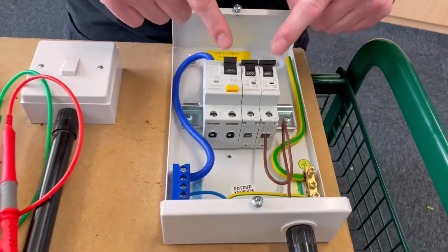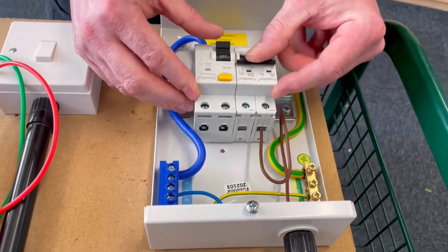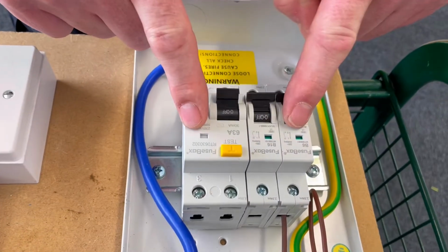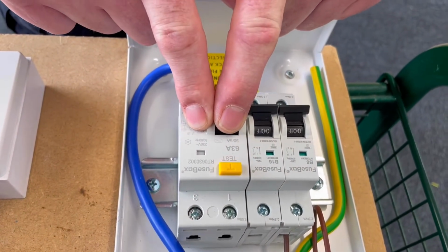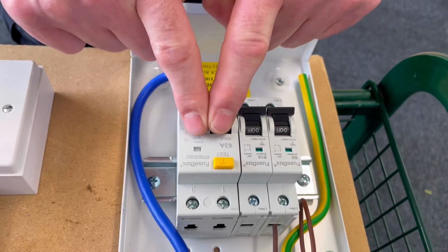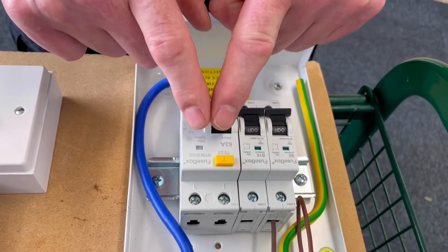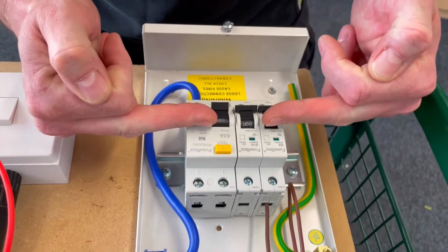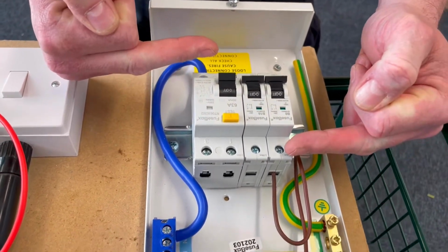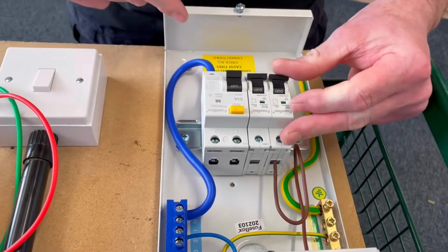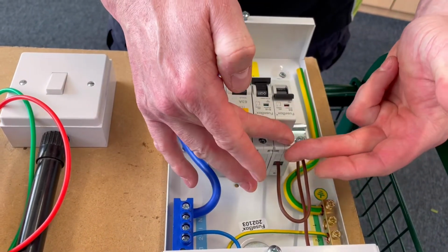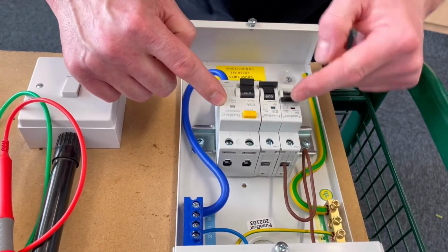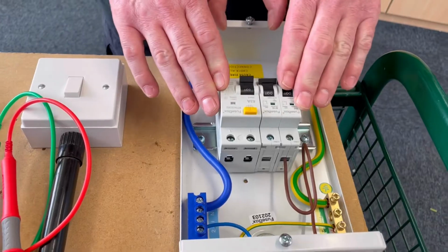So if we look in here, these are also effectively switches. So we don't want these switches in the on position either, because these components here, so this one here being an RCCB, contain electronic components, and we do not want to pass 500 volts DC through those because they could be damaged. So we're going to make sure everything is in the off position, and we're going to test from the outgoing side here with these off, because if we left it on, the 500 volts would pass up and through the circuit as well as down and across the bottom of the RCCB. So we leave everything in here in the off position.